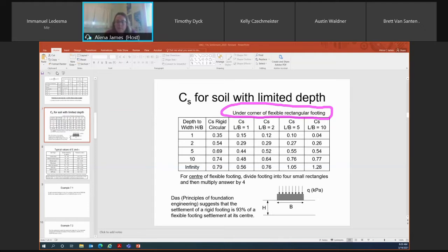Okay, would it feel like almost spongy? Like, is there just certain times of year you feel the sponge? It's like right now. Okay, that's probably not related to elastic settlement, because elastic settlement occurs almost instantaneously, right? So it would be when you immediately load a structure. So that's when your elastic settlement occurs. Right now, it's probably more related to the thawing of the soil around your foundation area.